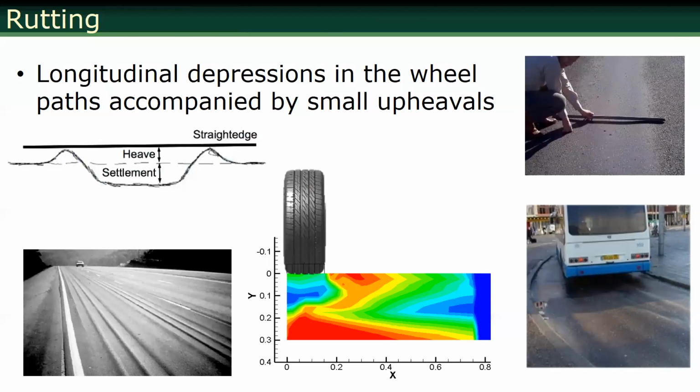But bad design could be as simple as you did not account for the traffic level. Your structure might be perfect, your materials might be meeting the Superpave specification, but if you use the wrong design gyrations, we're going to see this afternoon, for that particular road, you might just get this. Pavement design is traffic, climate, and material properties combined all together.